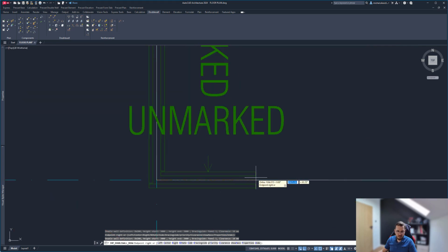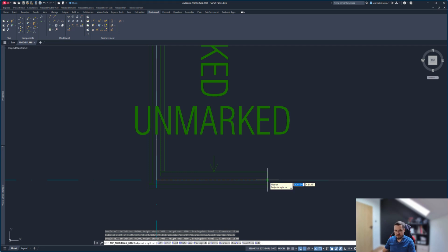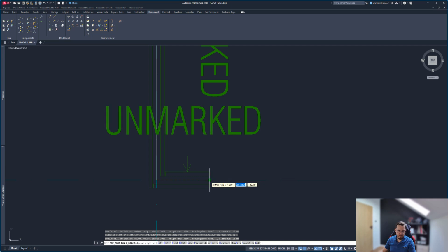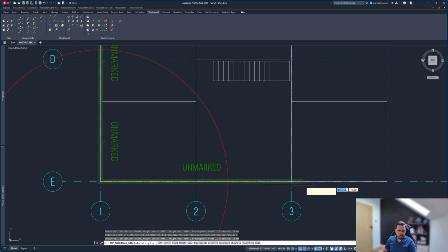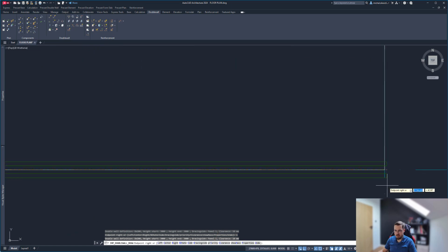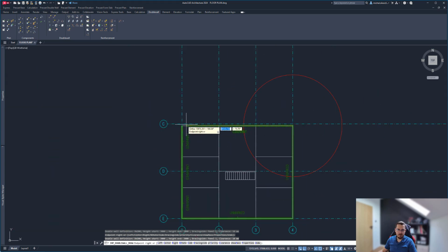One other thing, you can see that the joint between those two walls is automatically created. If I don't like the alignment of that joint, I can change the priority by selecting this option or pressing I on the keyboard, and you can see the priority change. So basically which wall covers which end face of a panel from which side, and like that. But now I don't have to click at every single point like this. I can just go straight to the end, straight to the end, and straight to the end.